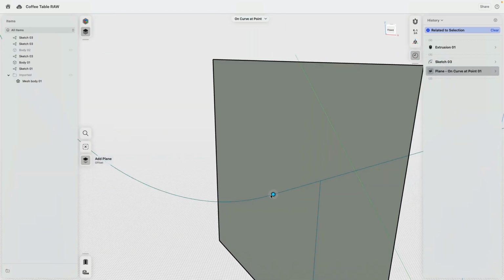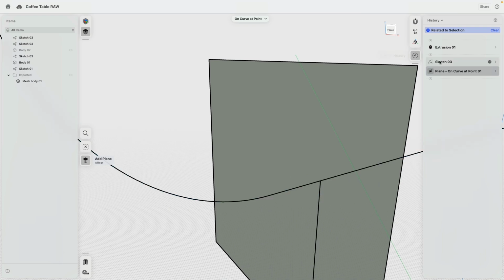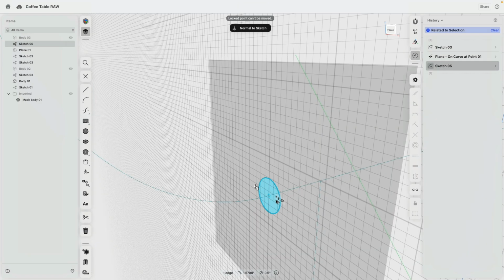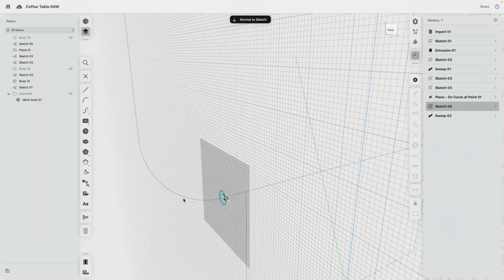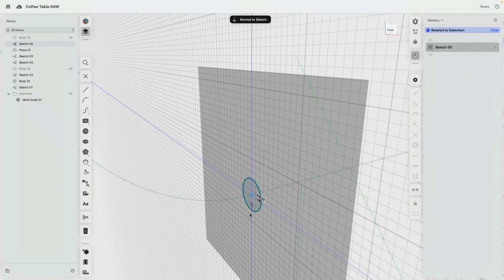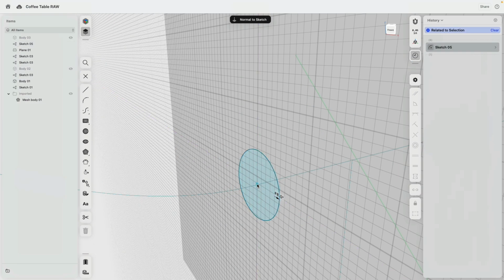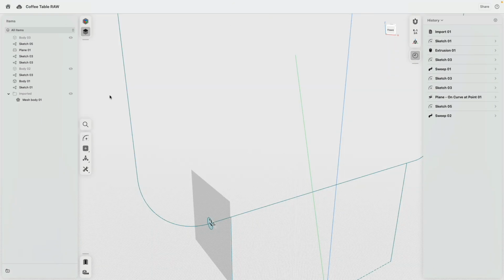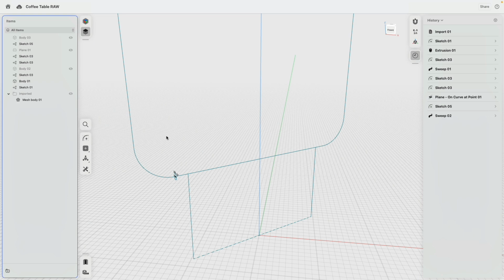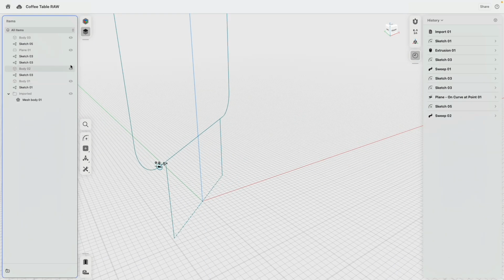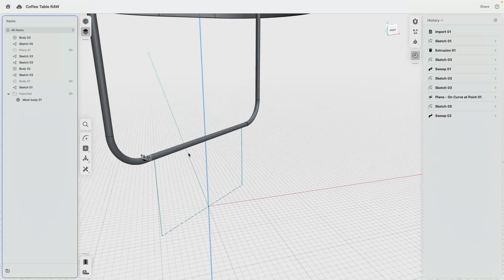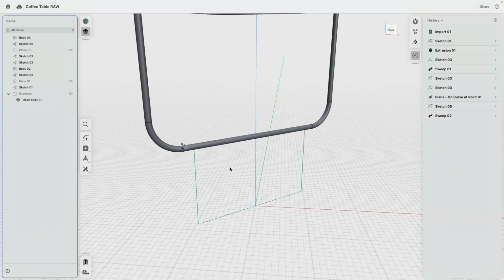So this is the plane. Okay, very good. There's the sketch. Oh, I think this actually fixed it. I delete this constraint and then there I recreate this constraint by dragging the plane onto it. Okay, that's how you can fix these annoyances. Good. So what do we do next?